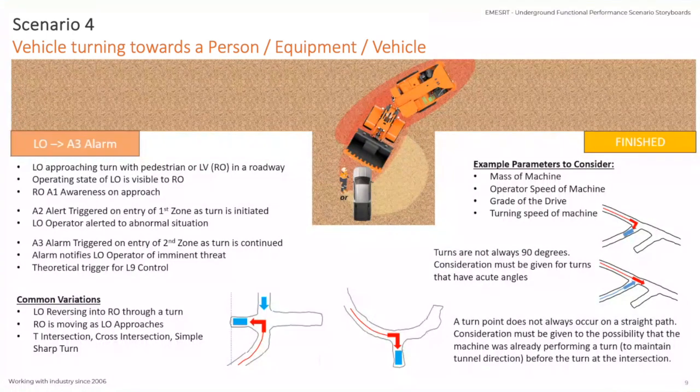We also have the fact that our turns, our cuts or our parking bays are rarely perfectly 90 degrees. Ideally, we do want that from a construction point of view, particularly from a ground support point of view. A perfect 90 is a lot easier to maintain ground support on.